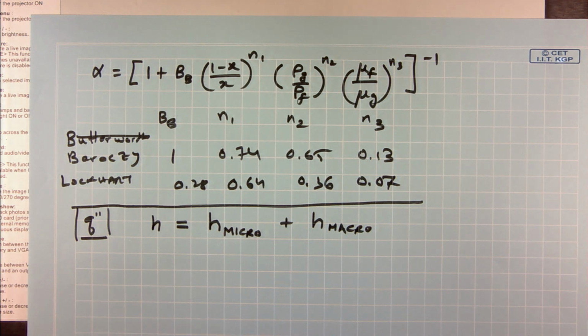Now what did he mean? What he meant was, if you look at boiling occurring in a pipe, let us say you are in fully developed nucleate boiling. The interesting thing about fully developed nucleate boiling is it is almost independent of the orientation of the heater. Whether you have a horizontal heater, an inclined heater, it does not matter, you will get almost the same value of fully developed nucleate boiling.